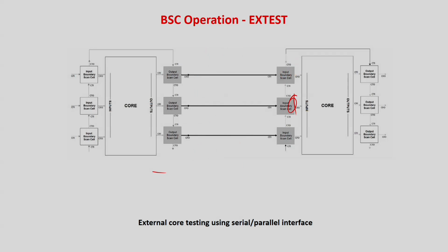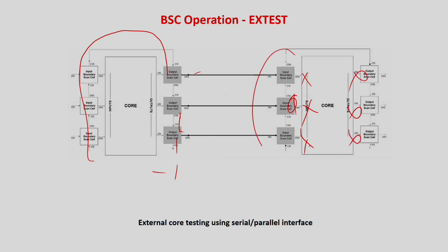In this case, what you are going to do is actually called EXTEST. You have to scan in the values of 1 1 1 1, and it will block these lines initially, get the values over here, and just do the XOR matching. So in this case this is called EXTEST. EXTEST is one of the very important instructions which is given to test the internal connections.